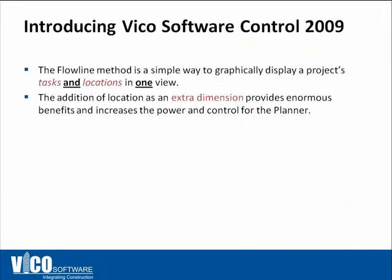So line of balance really means the ability to graphically display tasks and locations in one simple view, as opposed to just an activity-based schedule where you don't have locations represented automatically. Having location added as an additional dimension provides a lot of benefit. It increases the power of control for the planner, creates a deeper understanding of the relationship between tasks, and the planner can see what's going on in the schedule at a glance rather than having to spend a lot of time investigating multiple pages of printouts.